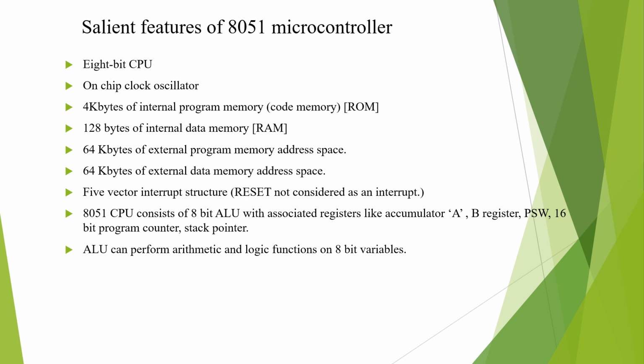Similarly, if we need more RAM, we can connect a 64 kilobyte external RAM as data memory. There is a five-vector interrupt structure. Reset is not considered as an interrupt in this case. We will discuss the five interrupts and their priority later.